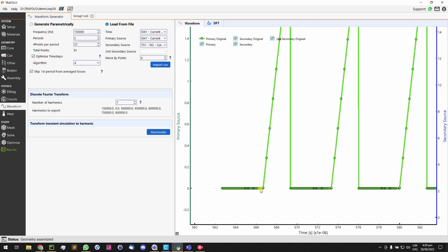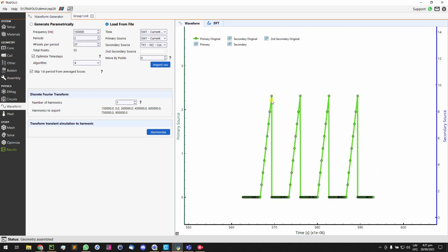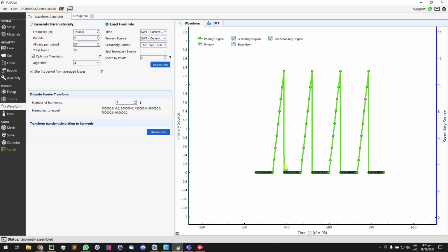For FEM simulation, it's just a waste to simulate that. But then you have a sudden change in the current, so it goes up to the maximum. And there's only one point here, and then it suddenly drops down. For FEM, this is like a nightmare. It will have a very hard time resolving the time derivatives for this sudden change, and might have issues with convergence. So what do you need to do?